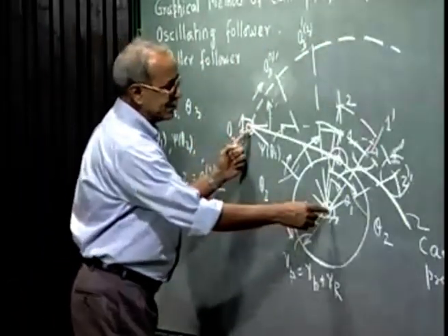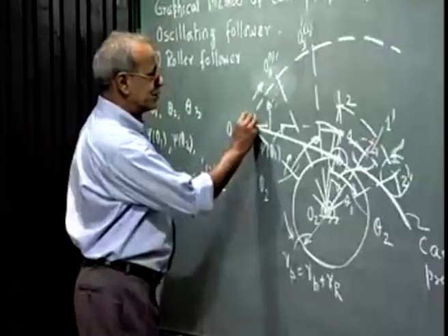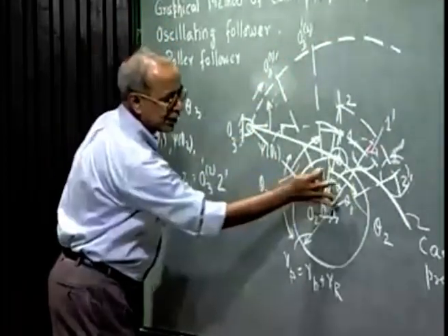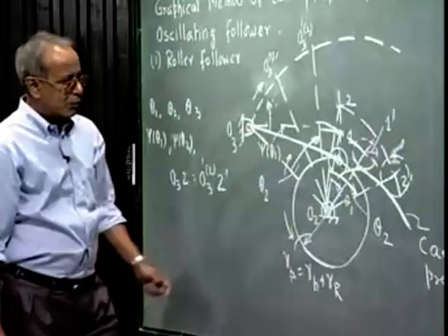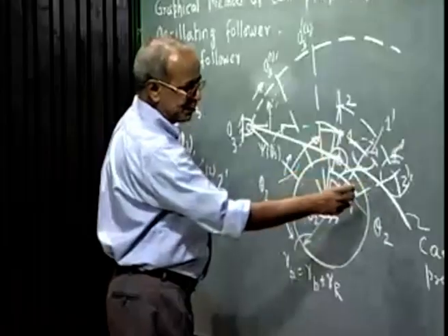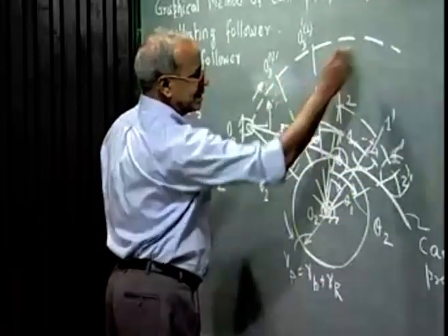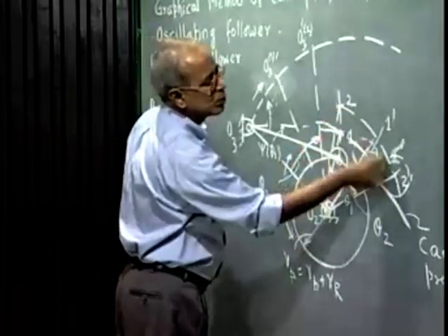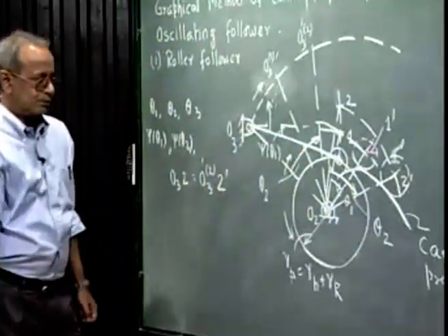It is actually this fixed link which is rotating. That means O3 is going along this circle in the clockwise direction when I hold the cam fixed. But from congruence of triangle, geometric construction can be much simplified by just not doing all this, only rotating O21 to this theta 1 and O22 through theta 2.